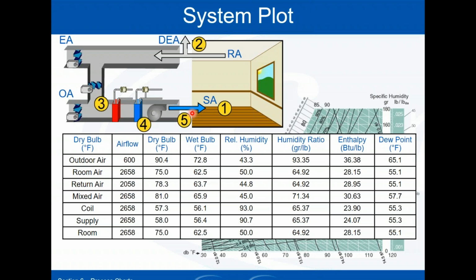Now, with that being said, if you designed the system for certain CFMs and based it on certain static pressures of all the static pressures I just mentioned, and then your filter gets dirty, or you take your filter out and you put in a filter that has a different pressure drop than was expected when we designed the system, that additional filter pressure drop is going to cause my supply fan to ramp up if I have a variable speed fan.